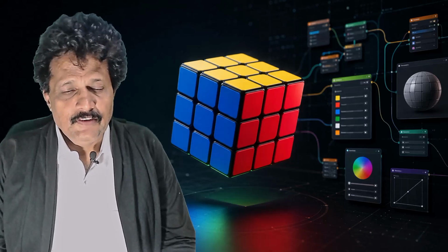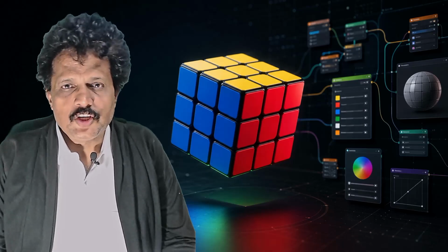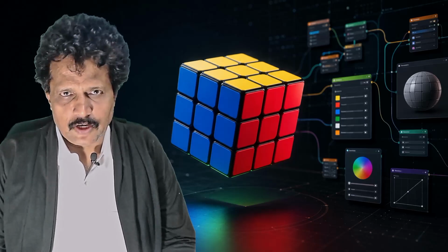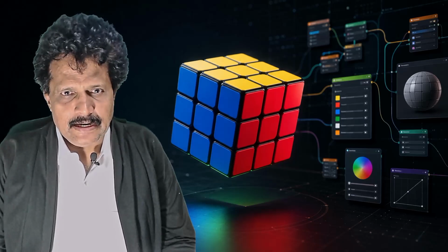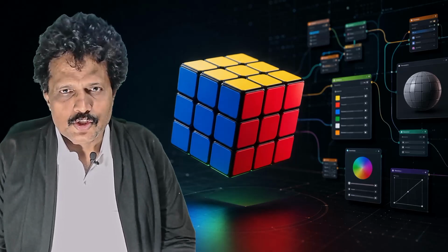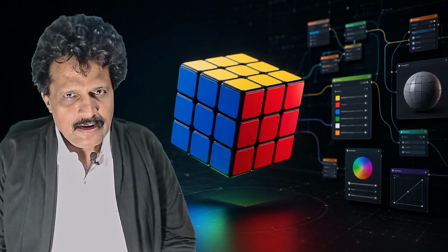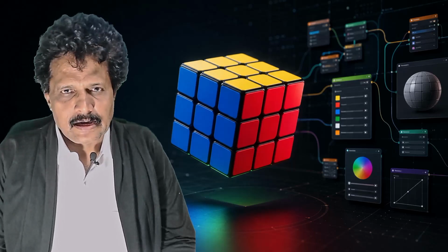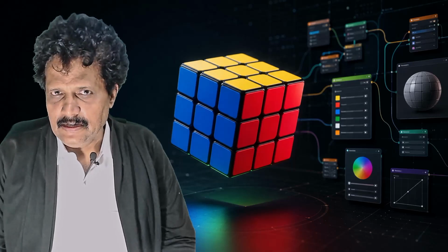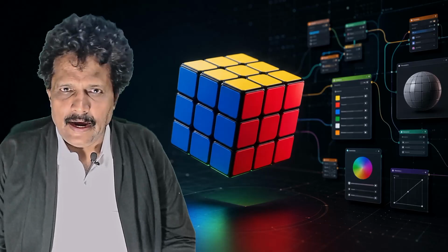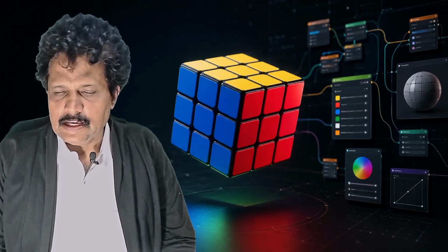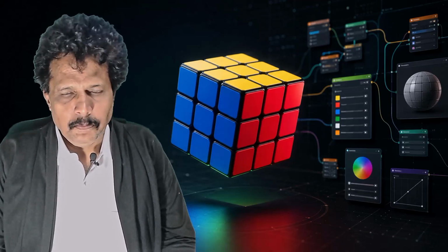In today's session, we will move from rotation logic to visual design. We will use geometry nodes to add color information to the faces of the cube. Instead of manually assigning materials face by face, we will do it procedurally. We will create a color attribute using stored named attribute. Then we will create a material in the shader editor and connect that material to our color attribute using an attribute node. After that, we will use index and compare nodes to identify each face of the cube and assign a different color to each face. This means every face color can be controlled by logic.